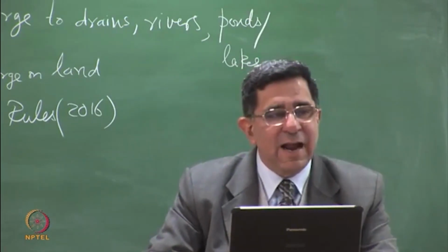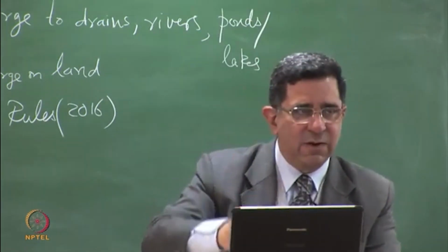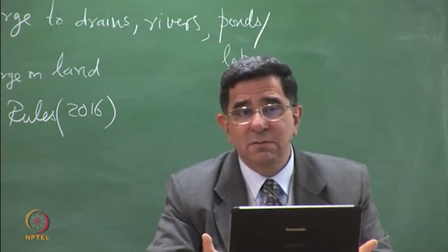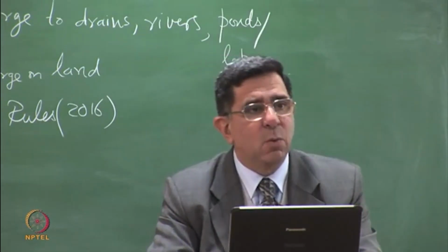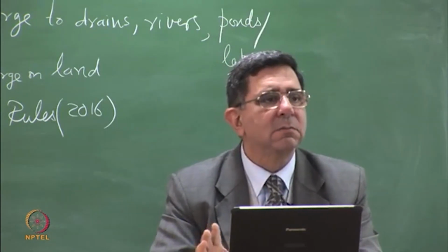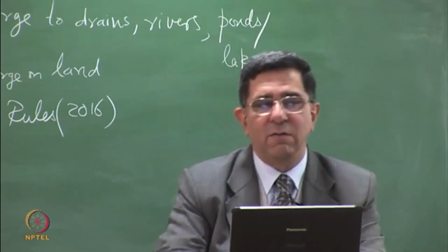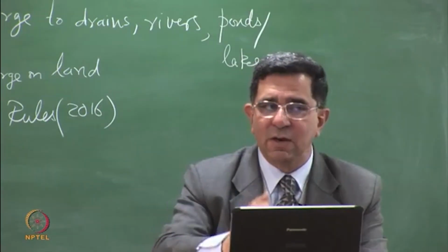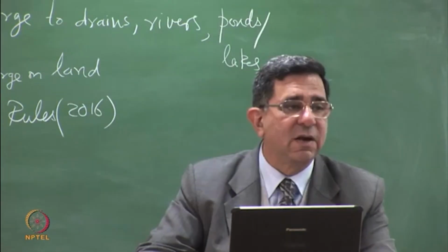The other way is that you make a landfill, you don't have the waste dump, you are not confident of your lab results. Make the landfill, store the leachate for 1 year. Leachate will come out. This is on an as-is-coming-out basis. Store it for 2 years. If you operate a landfill well, you're not going to get that much leachate which you can't store. If you operate it badly, then of course you have a problem because you can't store it. But if you cover it with a temporary cover during the monsoons and ensure that very little rain goes in, you can have leachate. And that you can test after 1 year, and then you can design any facility for that purpose.